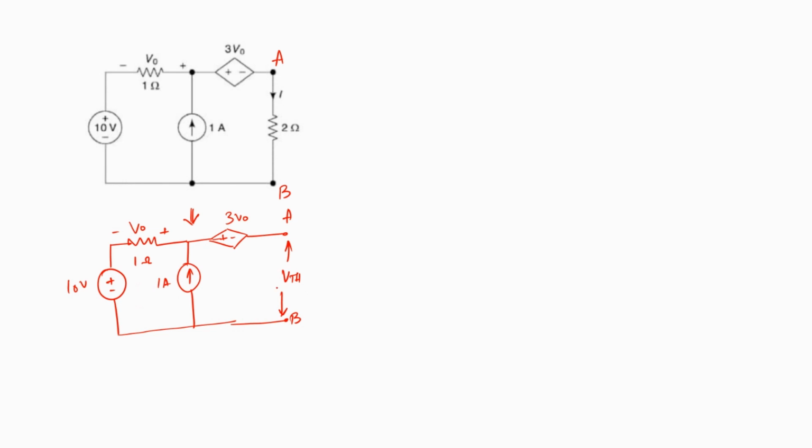Now, looking at this particular circuit with the open circuited condition, we see that there is a current source in between this mesh with the loop current I1. This could have been a potential loop, but now that it's open circuited, we can just assume that this is a voltage drop VTH available over here and apply the super mesh in this manner for this entire circuit, ignoring the current source.